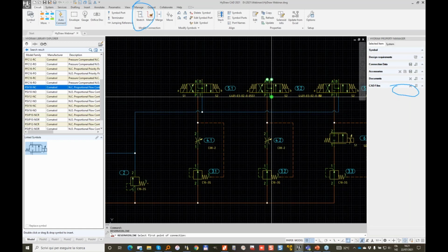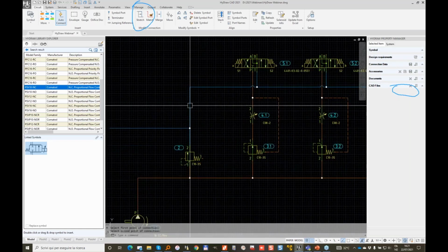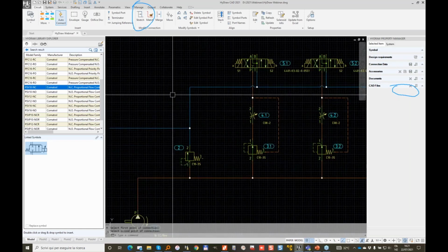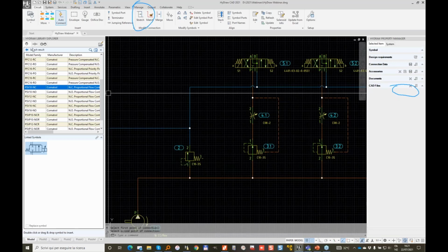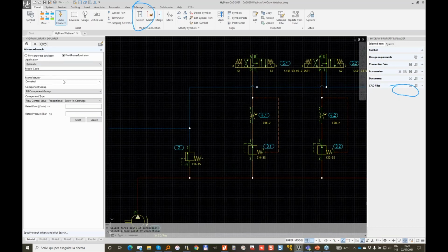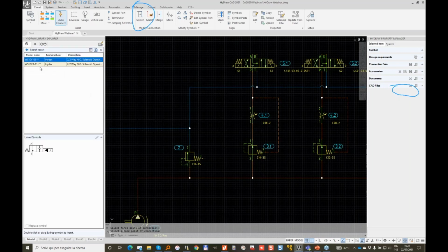and again tank line here. Let's say that we need electric unloading. So now I need, let me go for a HYDAC valve. So I take a WS10Y and search. And this one is okay. I just needed a single direction flow.